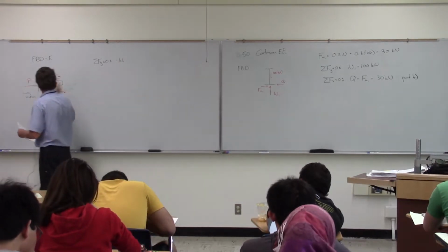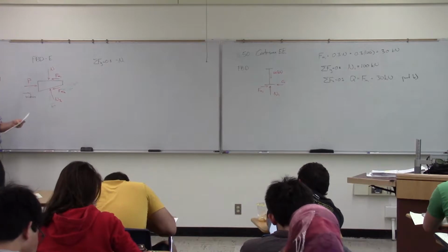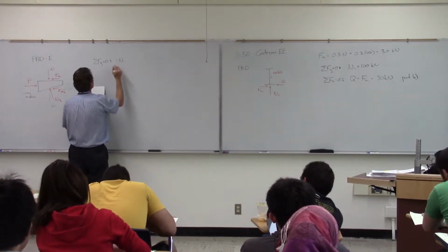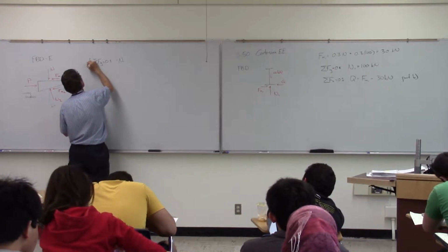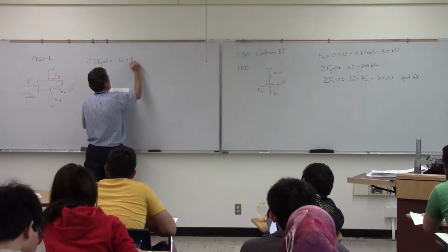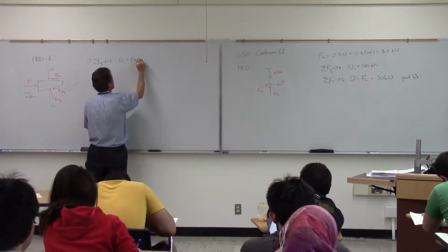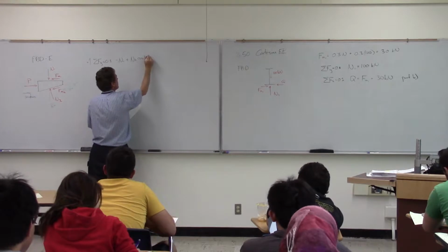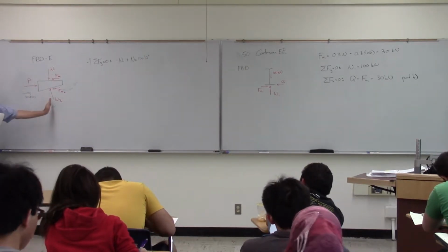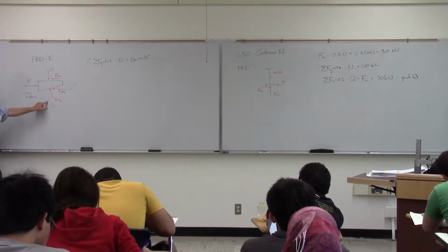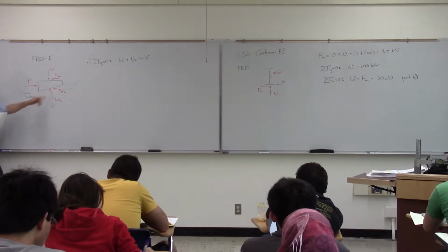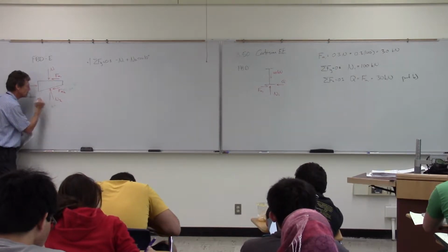And then all we're going to do is just collect the various pieces there. We've got the minus N1. And this is vertical, I guess. Okay, our N2, again, the angle, the 10 degrees is measured now from the vertical. So I'll be using the cosine times that portion. So I'm getting the vertical portion of that.